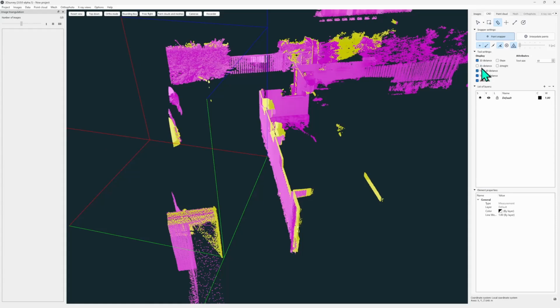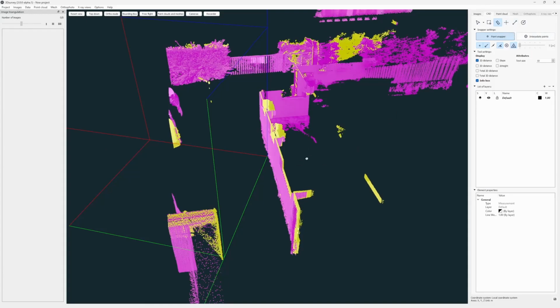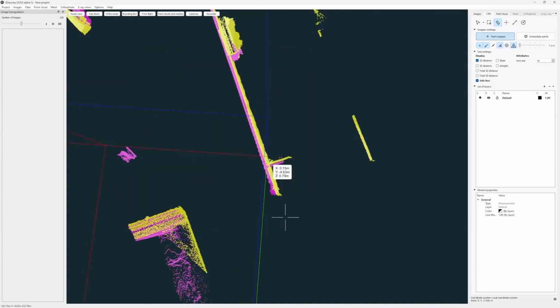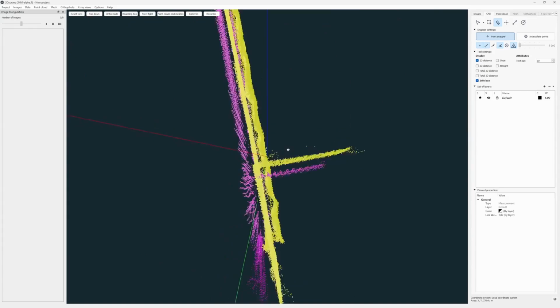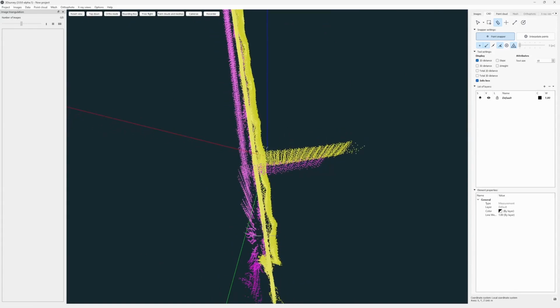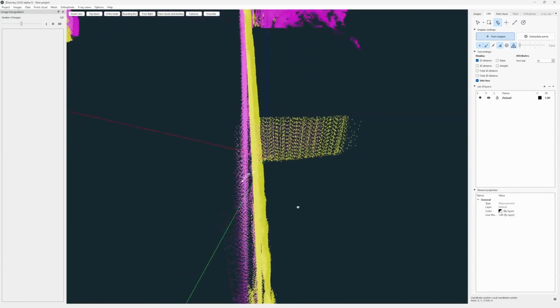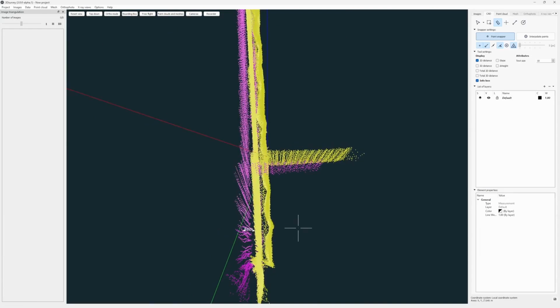So take the measurement tool, and we'll choose 2D distance because we're not interested in a vertical difference because Z-axis was actually locked. So now we just want to see how much difference there is between those 2 walls, and there we have our measurement.